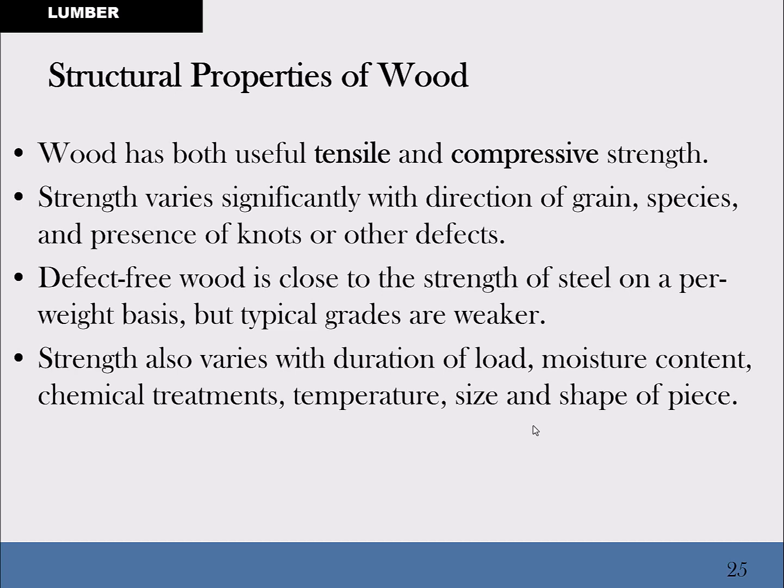Strength can also vary by the duration of the load. You can put a load on it for a short while, and that's a different thing from having a load year after year, where the lumber can slowly change shape. And then, of course, if there's high humidity, that changes how much load that wood can take, because it's going to have moisture, which means it's going to be more flexible, which is not always a good thing. You don't want your beam to be sagging. And if you put certain chemical treatments on, that affects it too. That can tend to make it softer.